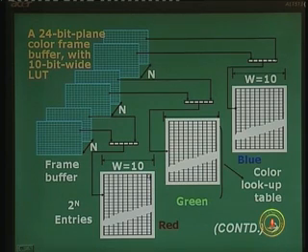Each entry 10 bit wide will be one color, red, green or blue, obviously, but the shade of that color will be 1 out of 1024 possible values, 2 to the power 10, 2 to the power W as we are talking. So 1 out of 1024 values will be loaded into each entry of the lookup table, and there are only 256 such values in one lookup table: shades of red, shades of green and shades of blue respectively. So these are the 3 different shades we are talking about, for 3 different reds, and now you can imagine these lookup table contents will be passed on to the electron gun. I could not put it all in one slide.